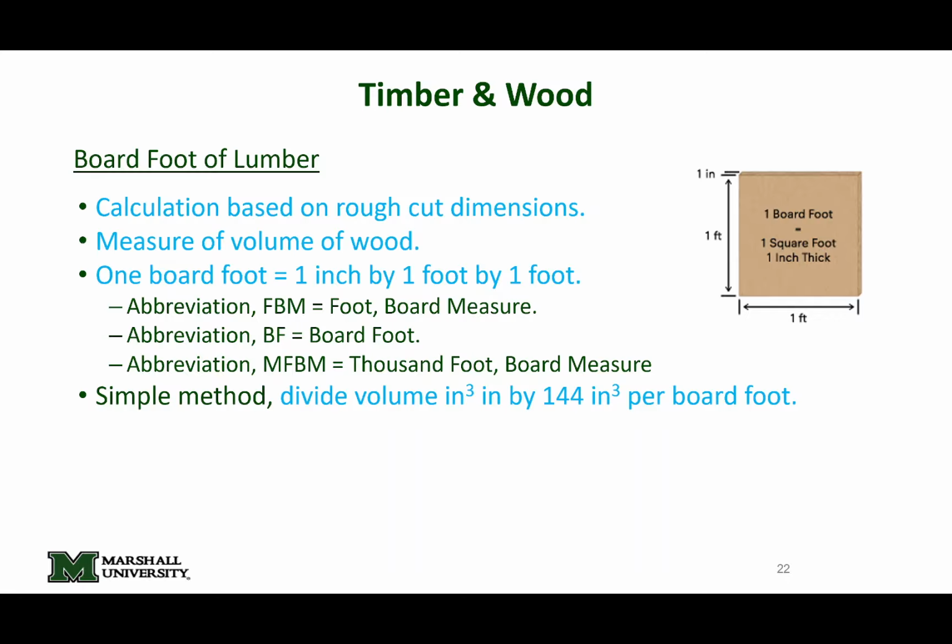The board feet computation is we just take the dimension 2x4, and by the way, we're using nominal dimensions, so we're not using the 1.5 by 3.5. We multiply that by the length, multiply that by however many of them there are, and we need to convert one of these to feet, because this is in inches and this is in feet. So just divide the whole thing by 12. That's a board foot calculation. That's it.